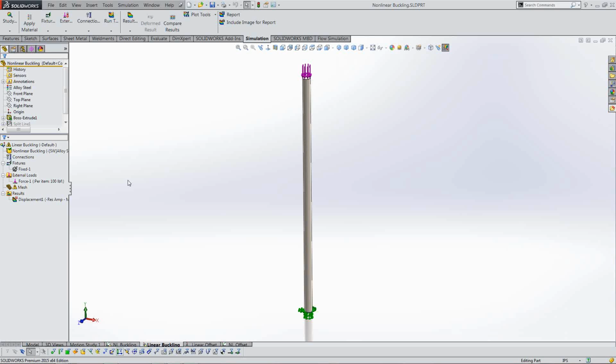It's going to typically predict the buckling occurs after it would have occurred in reality, just because of the fact that buckling is a very nonlinear type of process. And the linear tool will give you some insight into buckling, how it's going to occur, what the magnitude of the load is, but just keep in mind that it's non-conservative, and if you're using it in practice, you want to make sure that it's multiple times higher than your safety factor for structural failure due to yield.